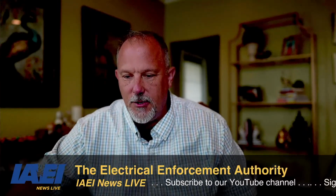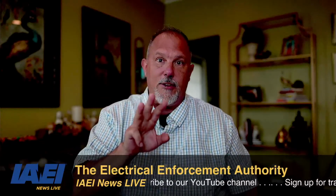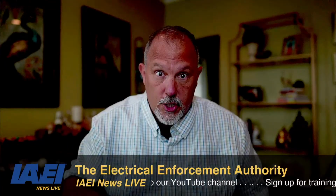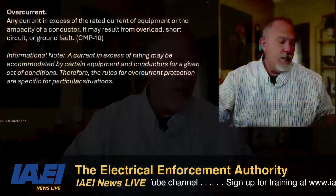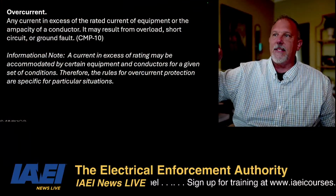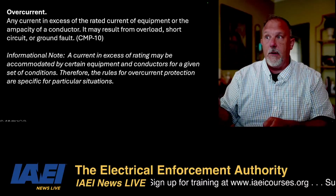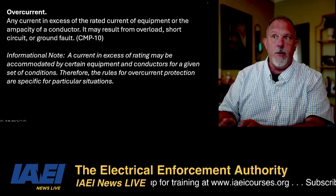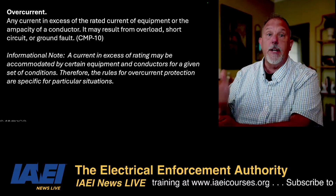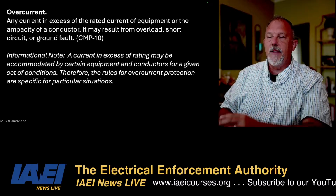Three parts to overcurrent, ground fault, and overload, or any of three, right? Yes. So remember, there's three parts to that. If we take a look at overcurrent, any current in excess of the rated current of equipment or the ampacity of a conductor, it may result from overload, short circuit, or ground fault. So any one of those, if it's an overload, it's an overcurrent. If it's a short circuit, it's an overcurrent. A short circuit may not be an overload. And same for ground fault, all that good stuff.